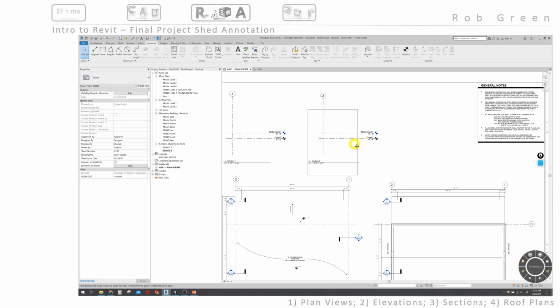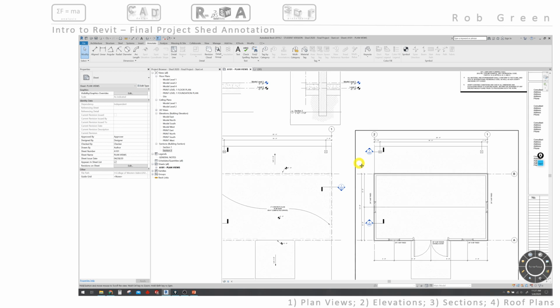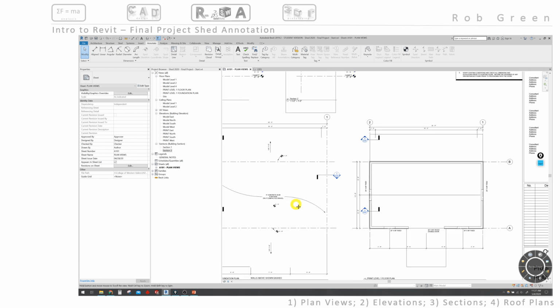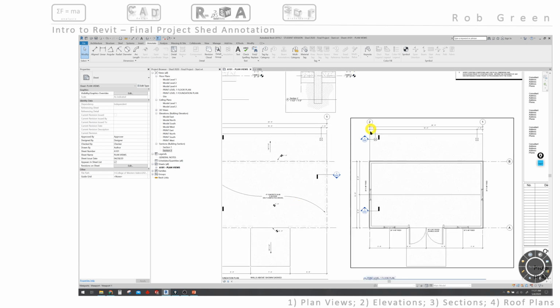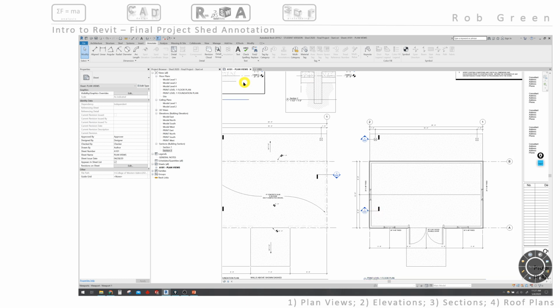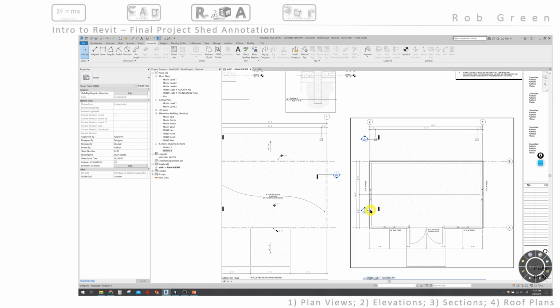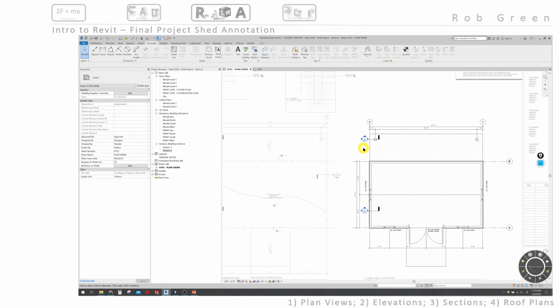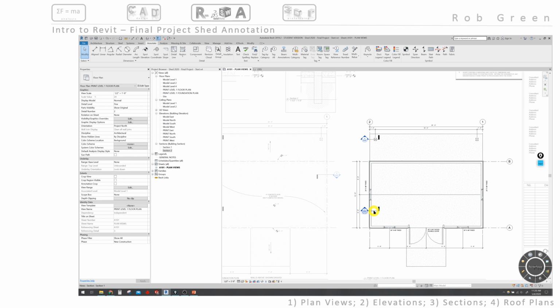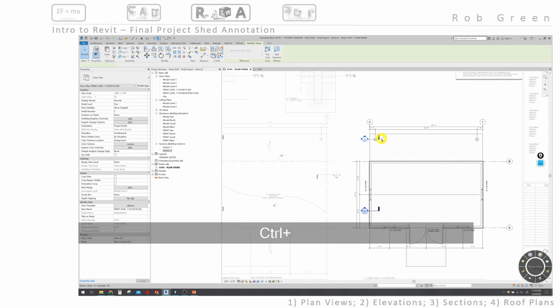What I want to highlight before I close this video is that the sections that I have created in these sessions show up now in my floor plan, and they are section views that are both specific to the foundation plan. So I don't want those section views showing up in an architectural floor plan. So I'm going to edit this floor plan and hide these two section views.